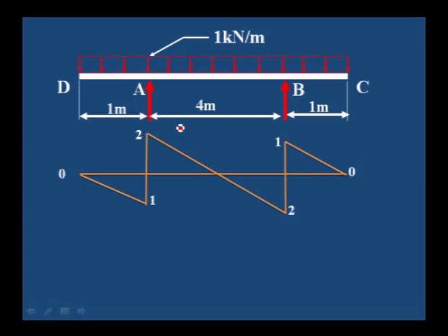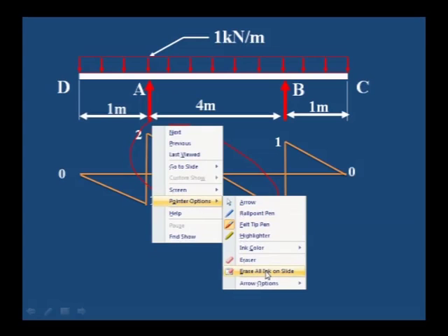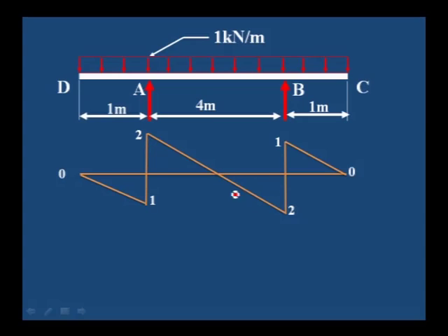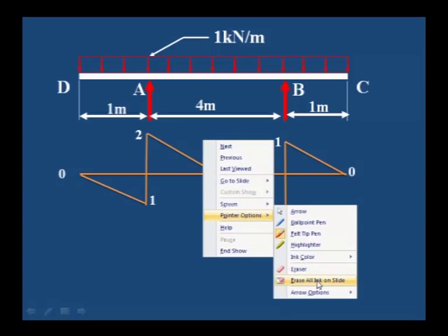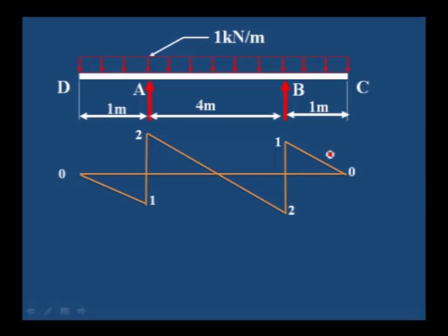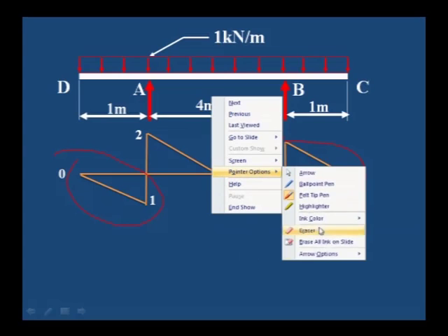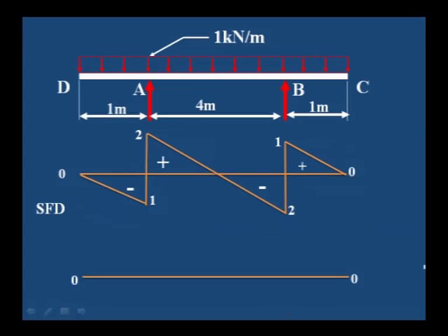Afterwards, if you draw the shear force diagram, you can observe here the central portion is the simply supported portion, and also everywhere it is sloping because it is a uniformly distributed load. Shear force changes its sign exactly at the center since it is a symmetrical loading, and two overhanging portions you can see. Just like a cantilever beam, this entire bending moment diagram is a parabolic curve, and it is having two points of contraflexure.